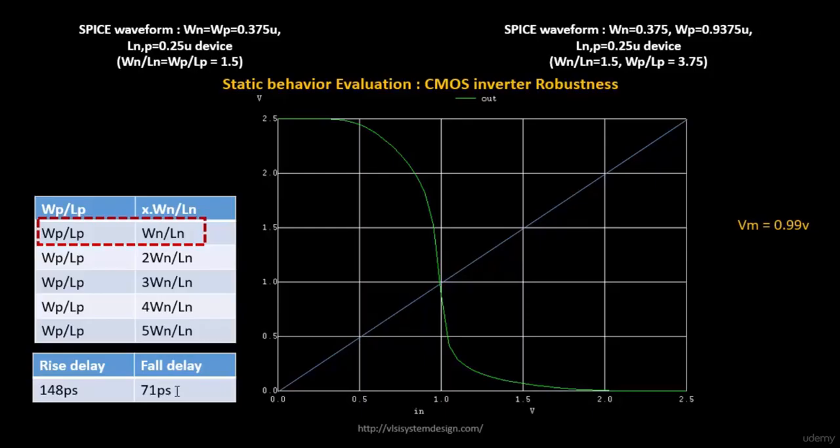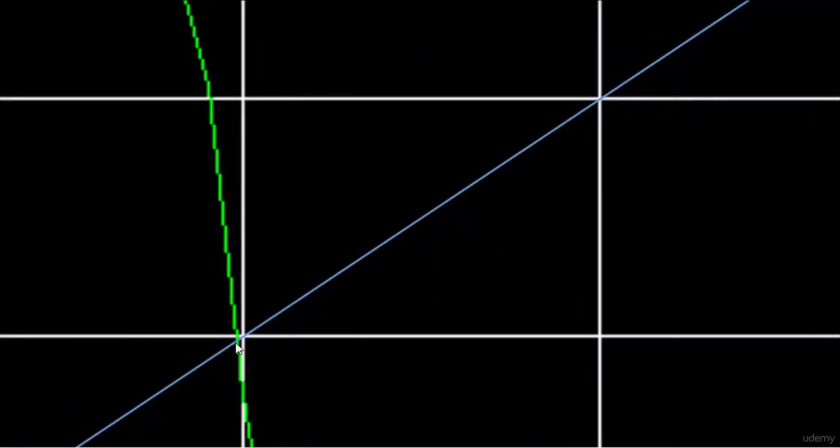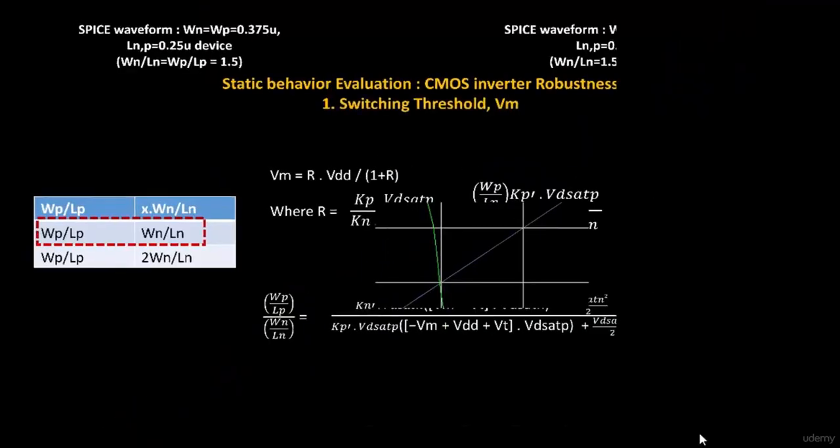We need to plot the input as well as the output waveform to calculate the delay. When you calculate the delay, it's basically from the point at which your input crosses 50% to the point where your output crosses 50%. Let me show you that. We'll plot out versus time, and the input waveform. So this is what I meant. It's not clearly visible, so I'll make it visible. This is your input, and this is how your output switches.